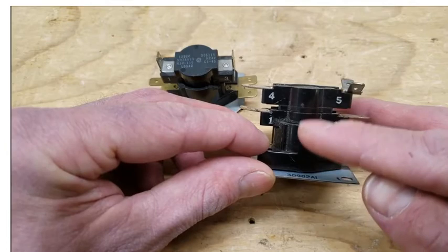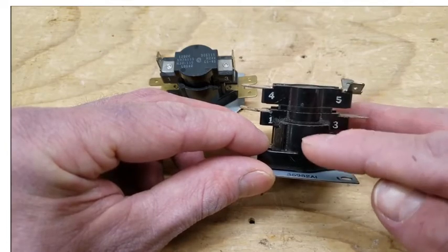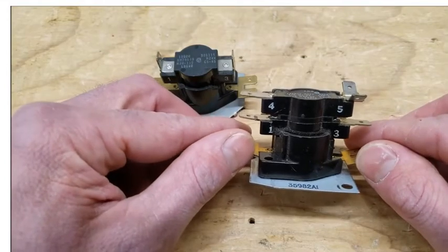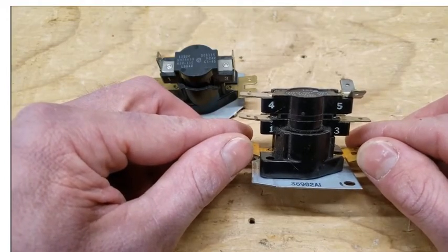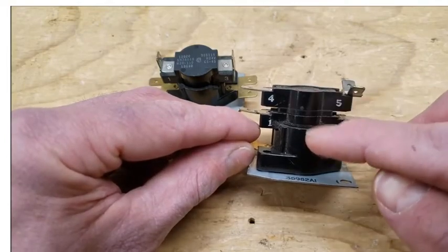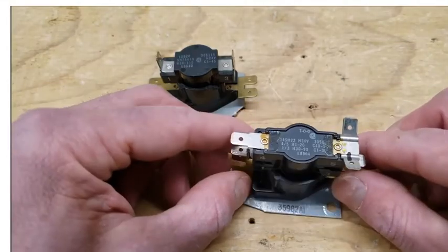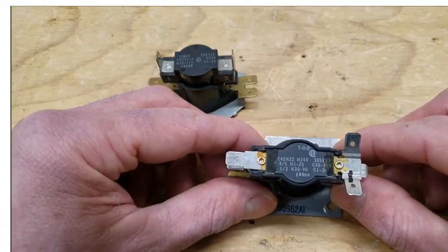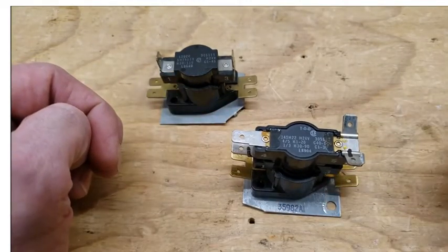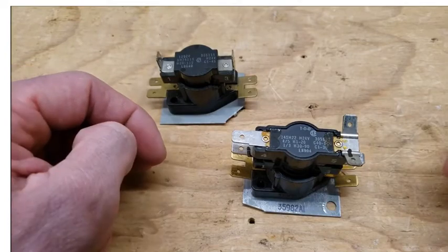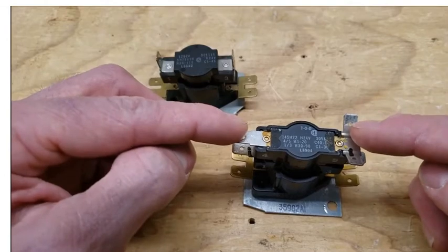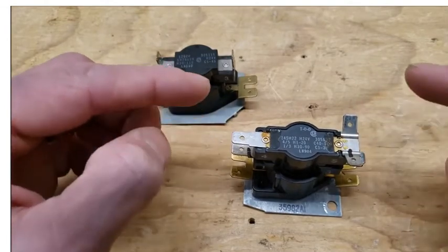Now those rods are a little offset from each other, so there's 2 rods side by side, and there are going to be these time requirements. So 1 to 3 is going to be a different time requirement than 4 to 5, just because of the position of the 2 rods inside. So up here at the top you see 4 to 5, and then next to it you see H1-20. So what that means is that it's going to take 1 to 20 seconds for these contacts right here to close after powering the sequencer.